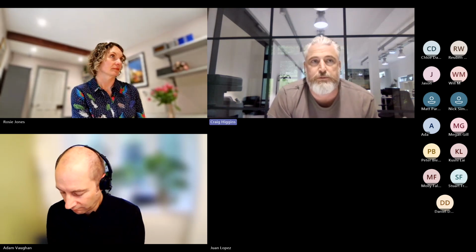Craig, there's a question here in the chat from Will saying we're seeing a lot of cost and carbon in the ground. Any top tips on reducing significant concrete infill? Weight of the building is often mentioned. Yeah, so the carbon in the ground, carbon in concrete is something which will exist and you can't really get rid of. One of the things the I-struct is a little bit ahead of RIBA on is in terms of not just measuring carbon, but trying to reduce the embodied carbon.